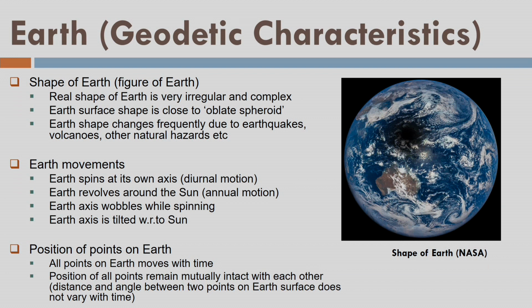But now for large areas, we should consider two important factors. One is the gravity potential, because at each and every point on the surface of the Earth, gravity varies. And remember that we are using the direction of gravity to measure our vertical heights. Then we should also take the 3D observations simultaneously. That means I should not separate two-dimensional survey and one-dimensional survey at any cost. If we acquire the 3D data simultaneously, that is x, y, and z, where we also consider the gravity potential of each and every point, that will be the wonderful and the best approach. So, let us look into this.